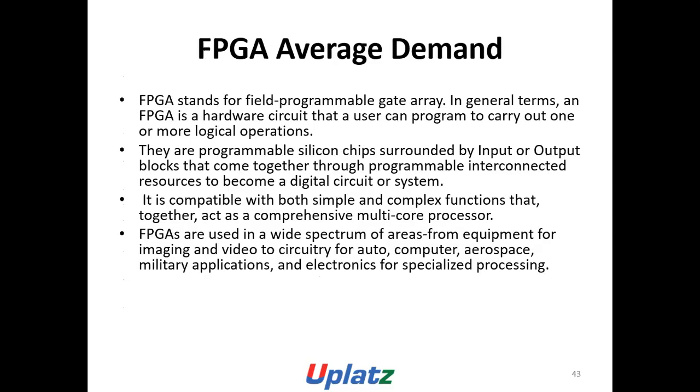FPGA is another average demand skill for embedded system engineer. FPGA stands for Field Programmable Gate Array. In general terms, an FPGA is a hardware circuit that a user can program to carry out one or more logical operations. They are programmable silicon chips surrounded by input and/or output blocks that come together through programmable interconnect resources to become a digital circuit or system.